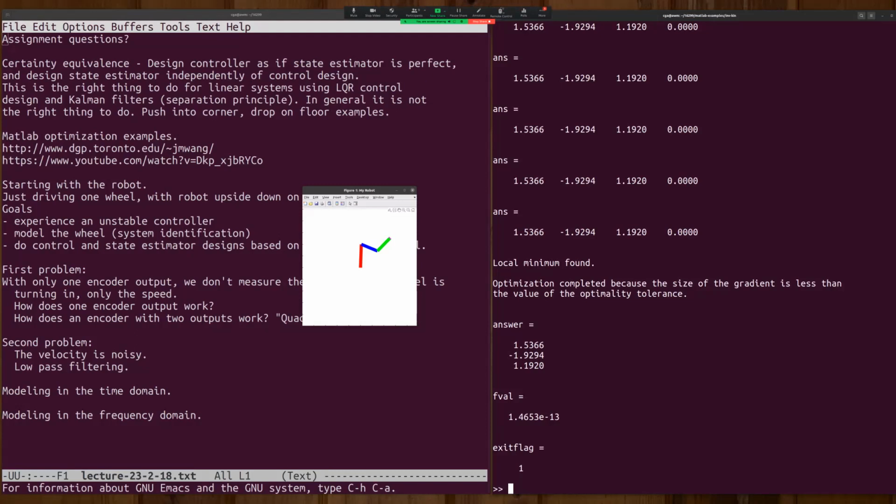Okay, let me rephrase that a little bit. You want the endpoint to hit the pink thing, so you're going to penalize that distance. And the way we typically penalize that distance is we square it. And you said, well, we could say we want this blue thing to be horizontal with respect to the x-axis or something. And we can use forward kinematics to figure out the angle of the blue thing.